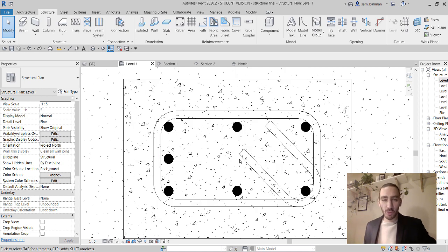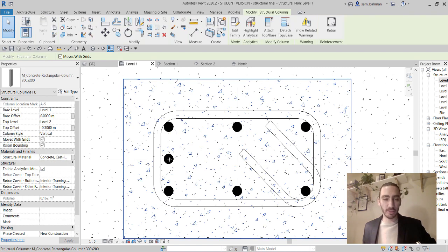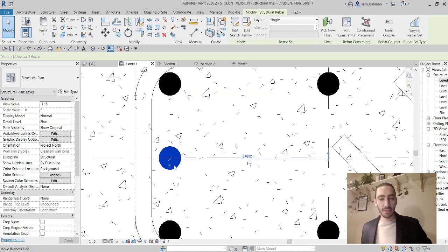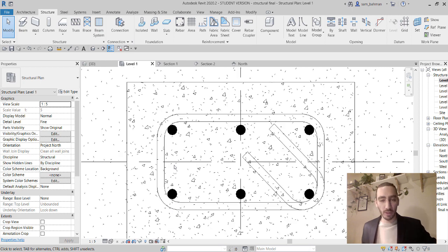Now to just give you guys a harder or more difficult sort of example to just make sure that you guys grab this material, instead of having one rebar getting left there, I want to add 2 rebars there, right? So in order to do that, I simply gonna remove this rebar by hitting on tab till Revit find it. Okay, simply remove this one.